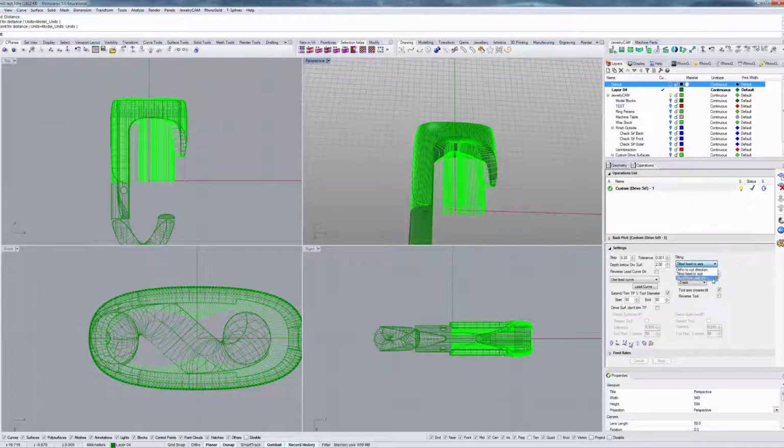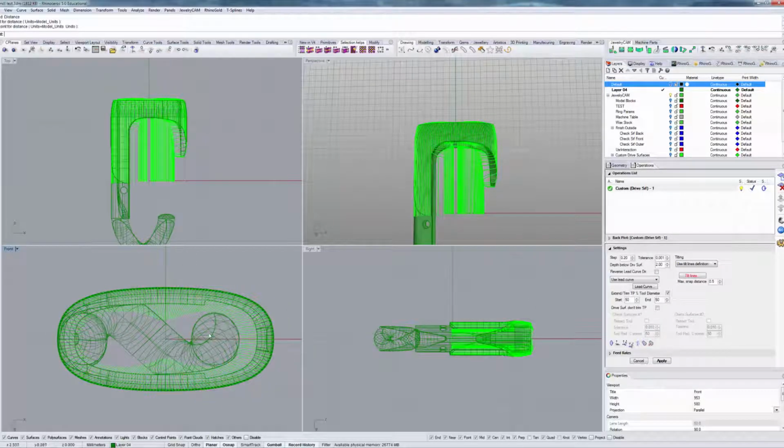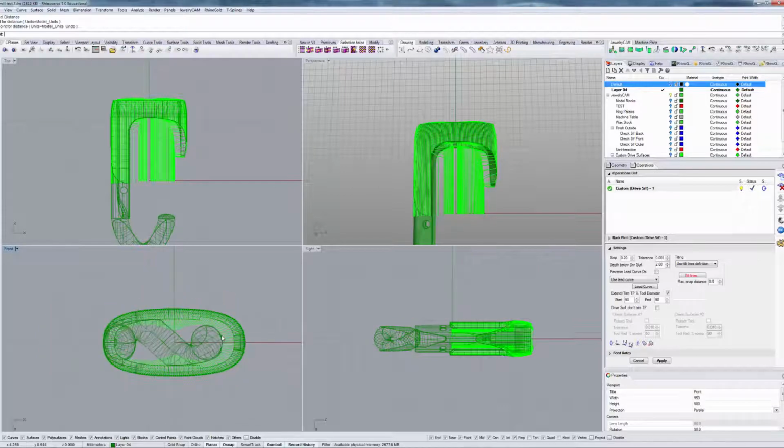You can even get more sophisticated using tilt line definitions. If you recall from our cut and curve instructions and engraving instructions, we could specify lines as vectors, meaning that at different areas of the model, we could specify which angle the tool should point at. So here, we could do the same thing.